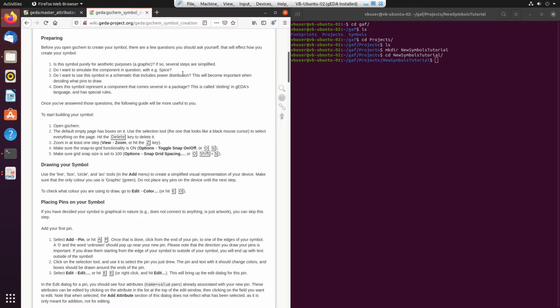What this means is, we'll come to this later, but essentially it means, do we want to define some pins as power pins or ground pins or something like that? Even though of course every PCB has some kind of power distribution system, in our particular case that's not going to apply. This component is going to be used in a system where there's a high voltage side, which is the voltage that we are going to measure, and a low voltage or signal side, which is the measured or converted voltage that is going to be processed, read, or used by